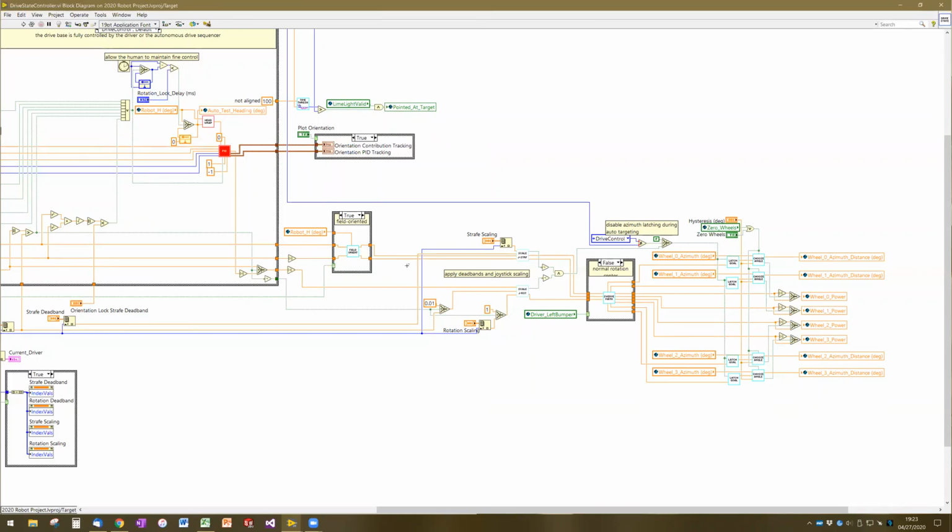Yeah, so exactly correct, Joanna. You know, the joystick values range from -1 to 1. Theoretically, if you're not touching the joystick, all the values should be 0. Usually we see them at about 0.02 or 0.03. Turns out that when you drop the joysticks repeatedly, that default value starts to get higher to like 0.05, 0.07.